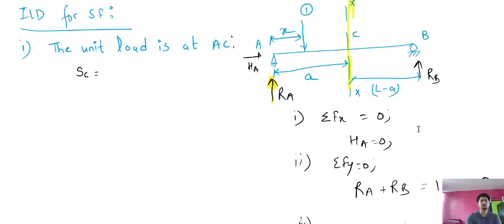Now we come to the shear force diagram. You have to get the equation of shear force at point C. Put your hand at point C and see the equation from the left hand side. I have covered this span with this hand, so I can see only reaction Ra and one unit load here. The shear force at C will be Ra minus 1.